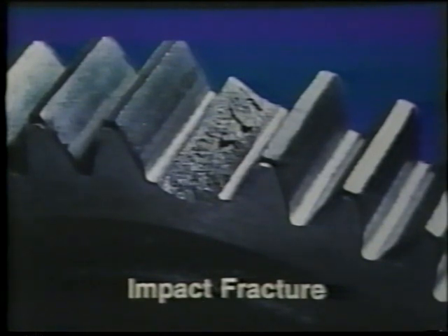Here you see an impact fracture caused either by a shock load or by a foreign object passing through the gear mesh. An impact fracture can be identified by a bump on the compression side of the fractured area. The more cycles the gear has run after the fracture, the smaller the bump will be. In addition to the gear which has a tooth fracture, the other 2 gears of that set should also be replaced, even though they may look undamaged. All gearing should be inspected for possible damage caused by the broken tooth running through the transmission.